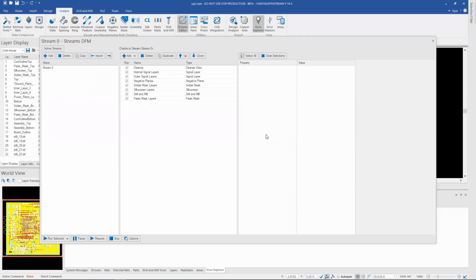Okay. So this is Streams RC, Streams rule checking. It's a checklist, and we call it Streams, and I think that confused a few of our customers, but it's basically a checklist, a play on our name. That's why we called it Streams. You can have as many different streams as you want to. Each of those can be made up of different checks, and we do it by layer type. I've split up inner and outer. You don't have to do that. You can always add additional checks here. I could throw a Netlist compare in here if I wanted to.